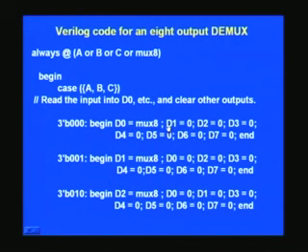And you notice that D1 through D7 are all made zeros here, because when it enters, it can enter from any other state. So, unless you make them zeros here, it may hamper the performance. It may have come from a latch, and it may latch onto the old signals, right, and it is better to give this here.